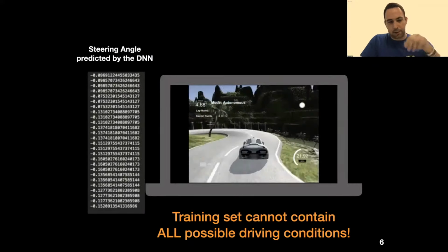Another notable result is that the correct misbehavior predictions are made 6 to 9 seconds in advance, which is quite enough to enable self-healing mechanisms, either by the driver or by another component. So just to conclude this overview, I presented to you SelfOracle, which is a promising technique that uses autoencoders to perform online misbehavior prediction for autonomous driving systems. The main highlight of this research is that it proposes the use of autoencoders and their reconstruction loss as a useful score to measure the unexpectedness of the driving scenario. Particularly in our experiments, the variational autoencoder proved to be the best.